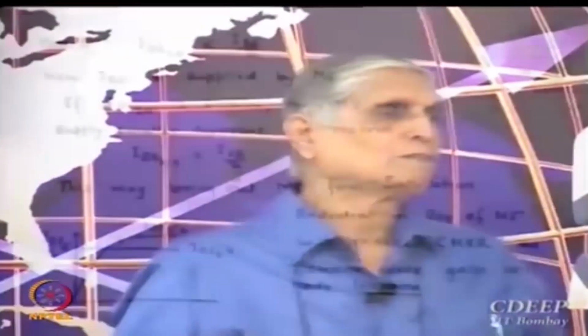Is that clear? So a case which looked very trivial otherwise has actually, though we have a differential feedback, we are connecting gate to the output. So we have a feedback, and in spite of that such a situation is not returning back, it is actually reaching one end. Okay. This is something not correct. So if I can make something common mode constant, then my CMRR will not be dependent on this situation. So let us see further, is that okay?